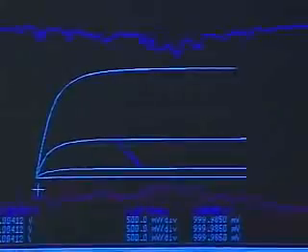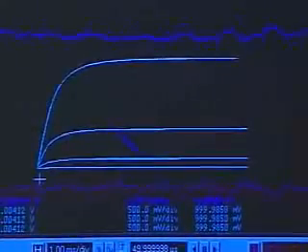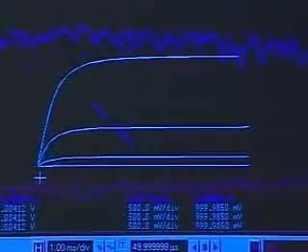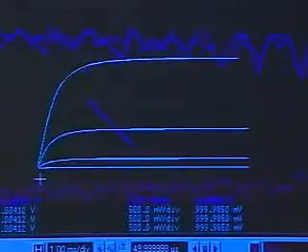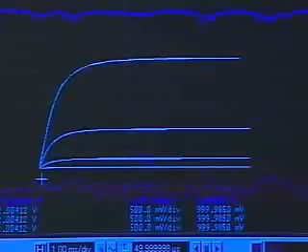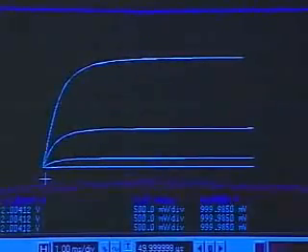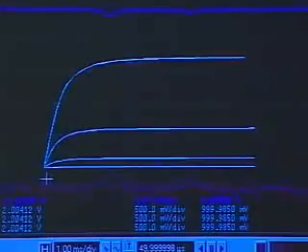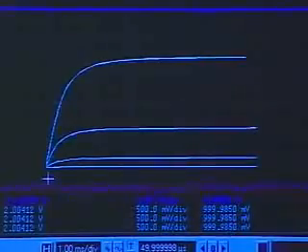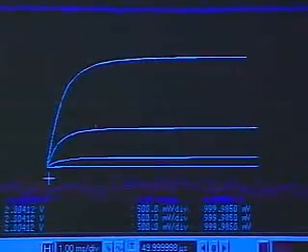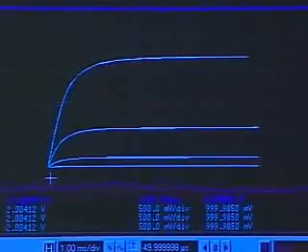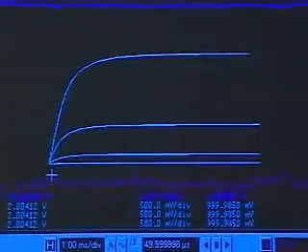So the amplitude increases by increasing the bias. Okay, now you should hear the volume go down and distortion. So notice now that the bias is way down here, so the gain is very low, and plus this is distortion because of cutoff. Now what I'll do is blast it up here, and you'll see that the volume has gone up, but then you'll see distortion again. And let's see if we can stand the volume here.